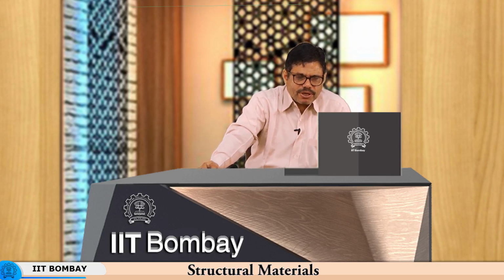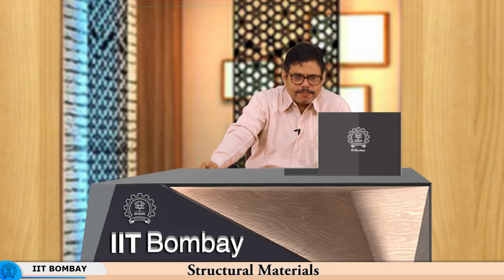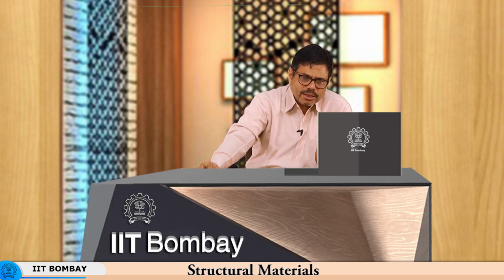So in fatigue failures, it is easy to identify the location of the crack or the initiation of the crack, and the fracture surface at the origin is usually smooth, because the crack originates either at an inclusion or at the grain boundary. All these sources appear very smooth, whereas once it starts propagating, you see the intense beach marks which are present over here, which is a testimony to the fact that the material has arrested the crack time and again.